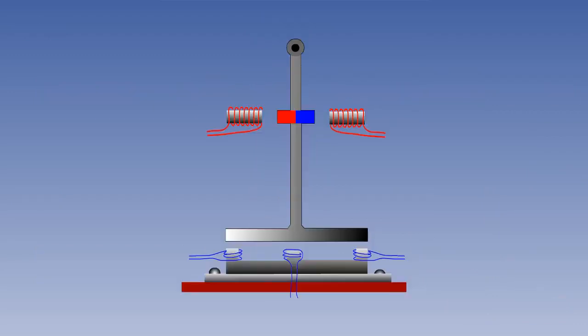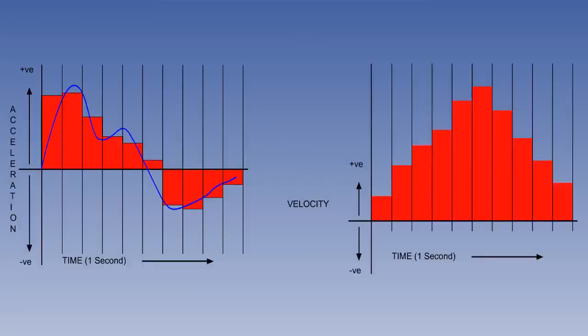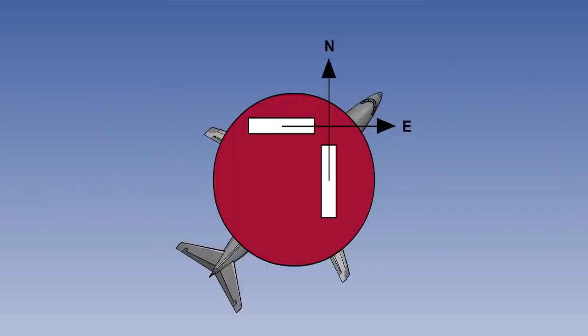Let's summarize the whole lesson now. There are various different forms of accelerometer, but the pendulous E and I bar type is a fairly common one. The actual mechanization does not need a long vertical bar, and practical accelerometers are usually a rectangular shape, with the long side horizontal. Integrators convert a rate of change over a period of time into total change over that time. It is essential that the accelerometers are mounted on a table that can rotate, pitch, and bank, called a platform, in order that they can be kept pointing north and east.